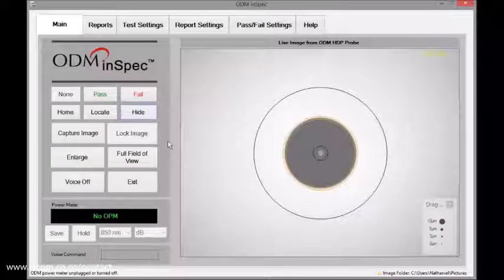For perfectly clean fiber end faces, it may not be necessary to use the drag here box. If the end face is completely clean or it passes according to the corresponding zone definition table, click the Pass button to place the pass stamp on the image. Before saving, be sure that the image contains the pass stamp, the grading circles placed correctly, and the drag here box. If those elements are visible, click the Capture Image button.